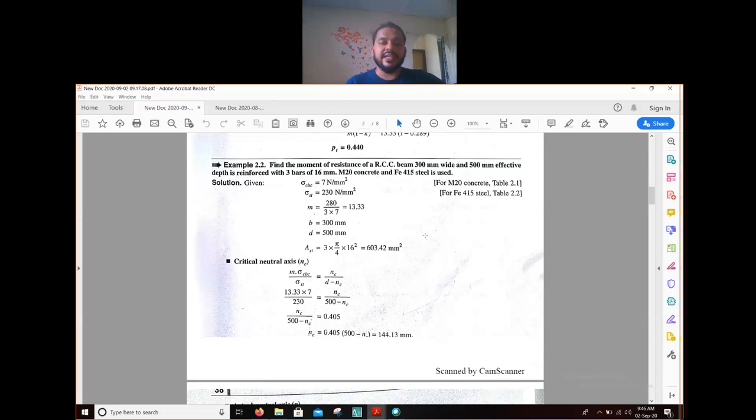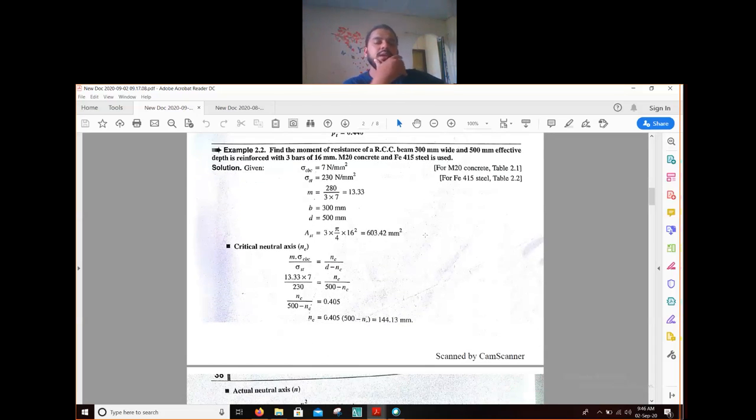Let us see the second problem. Read the question. Find the moment of resistance of an RCC beam 300 millimeter wide and 500 millimeter effective depth, reinforced with 3 bars of 16 mm diameter. M20 concrete and Fe415 steel is used. So we have to find out the moment of resistance now.